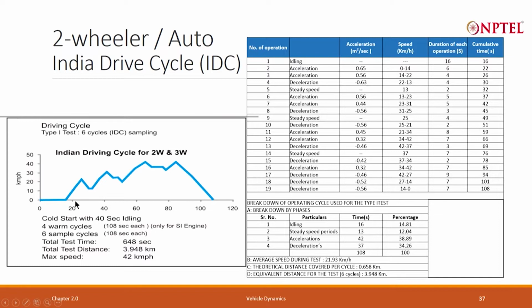Well, here itself it is broken into two. It is assumed 16 to 22 seconds it is at a certain speed, 0.65, then your acceleration slightly decreases, which does not show very well in the curve. Why does it not show? Because it is not a very fine curve, but this is the important thing. Acceleration is 0.65, acceleration goes smaller. Then for the next 4 seconds the speed is actually going down.